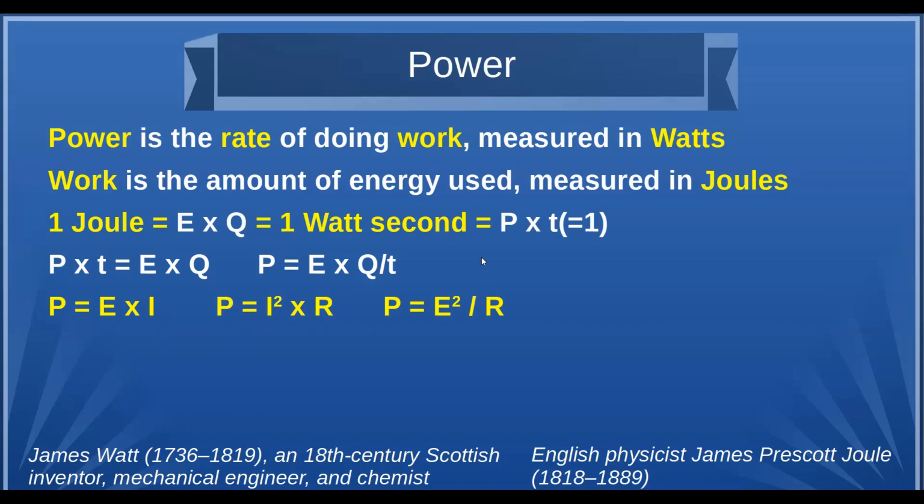Or if you play substitution with Ohm's law, it's equal to the current squared times the resistance. Or it's equal to the voltage squared divided by the resistance. So they're all things you can derive between the power equation and the Ohm's law equation by substitution.